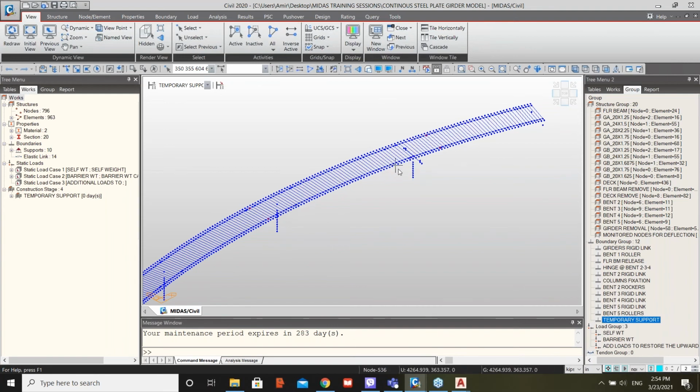Of course, the bridge was not originally designed for that. So the cantilevers are expected to have an upward deflection because of removing the load from this portion here. Having those tips of the cantilevers going up will push on the adjacent spans downwards and will increase the positive moment on those 2 adjacent spans. So in order to control the upward deflection at the tips of the cantilever here, we need to provide some temporary support or shoring at those points, such that those points are supported.